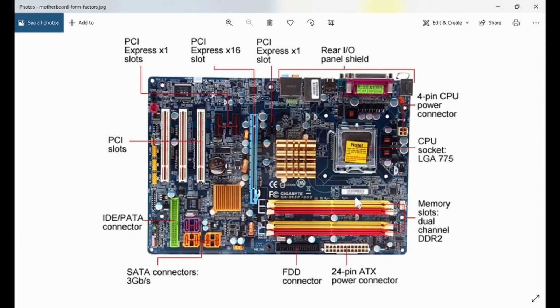And so because these 3 are super fast, very fast, we have decided to give them a special bridge. And that bridge is what controls their communications among themselves and sometimes to other components as well. By the time we finish learning about the components on the motherboard, everything will make a lot of sense to you. Right now, we are saying that the CPU is fast, the RAM is fast, and whatever will be connected to the PCI Express slots is also fast. Because these 3 are extremely fast, the North Bridge is dedicated to just these 3 components.